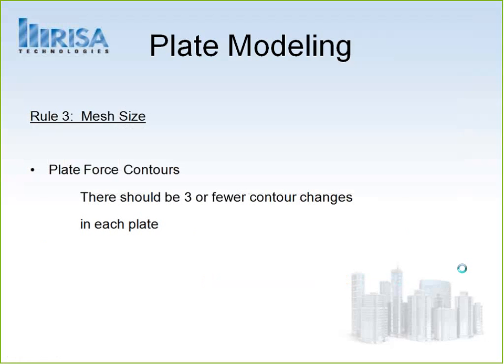Plate meshing is probably one of the important things, and when you start to dictate what the size is, the mesh change and the deflection changes might be even more important than things like size. This is also another thing where we're going to be dealing with the results side of things.